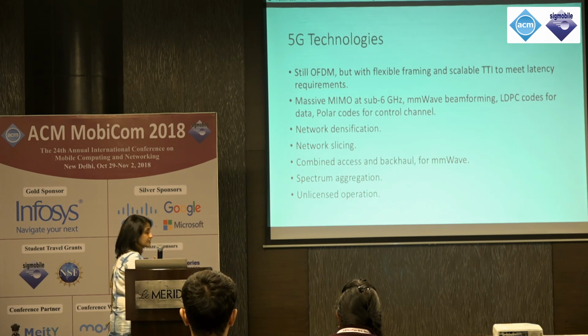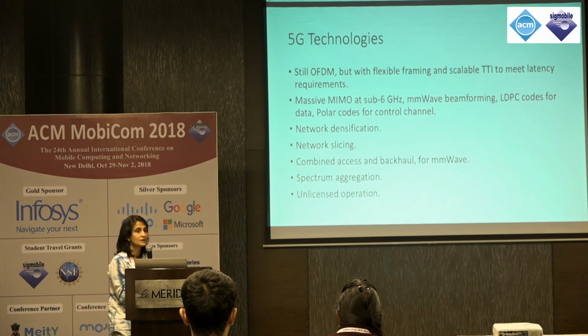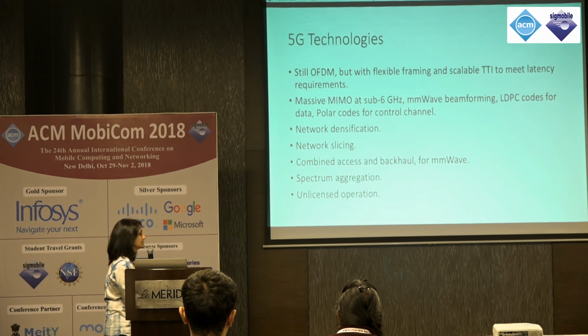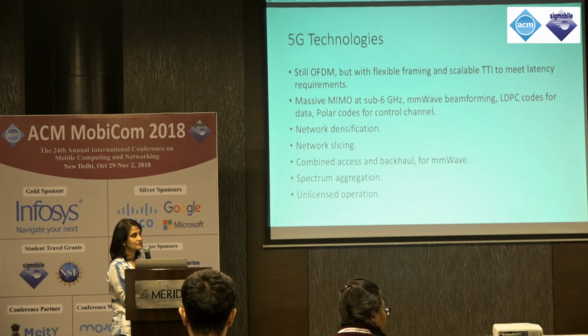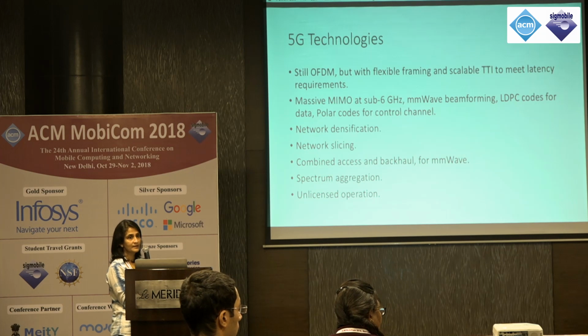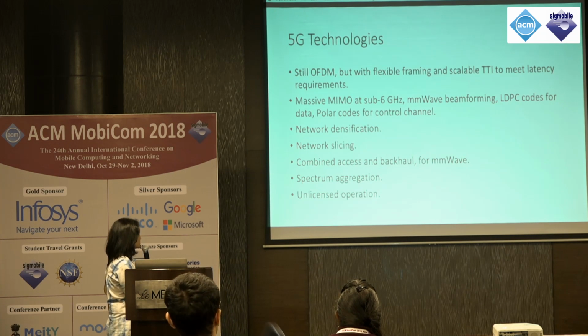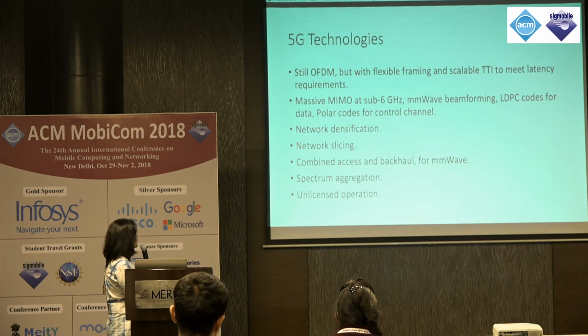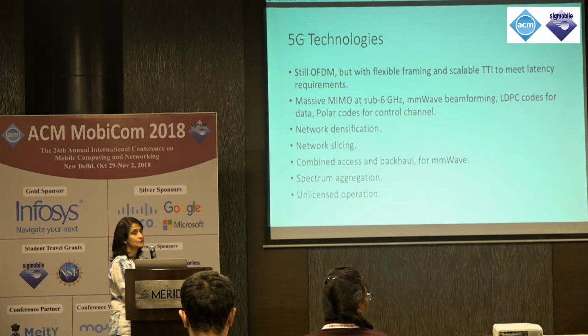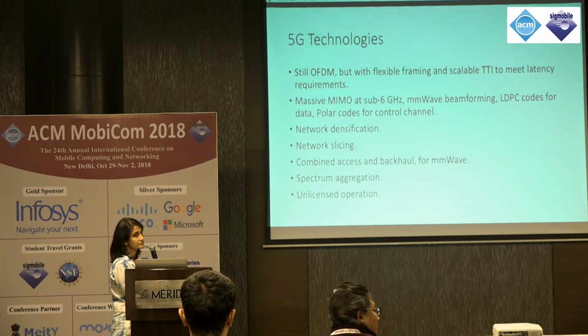The coding changed. Turbo codes was what LTE used through 3G and 4G. However, LDPC codes, the low density parity check codes, have pretty much become the industry standard for Wi-Fi. And for 5G, they decided to make the change to LDPC codes for data. And they picked a new kind of code called polar codes for the control channel.